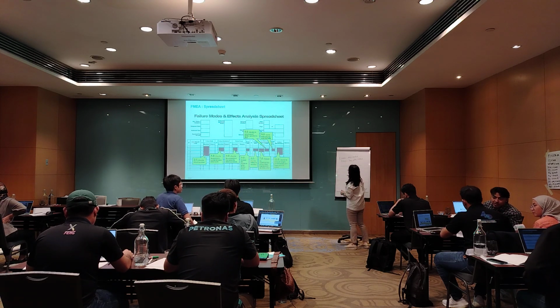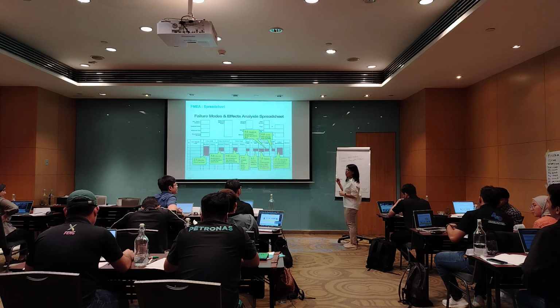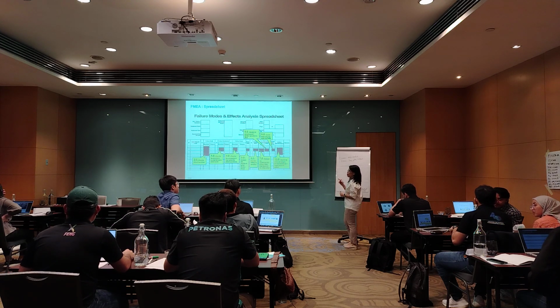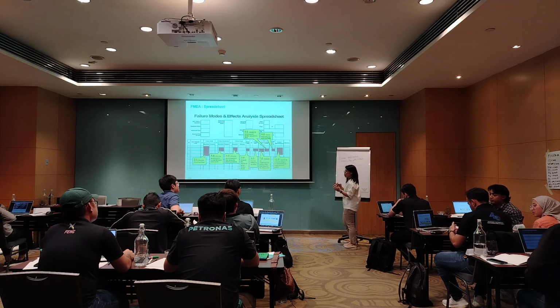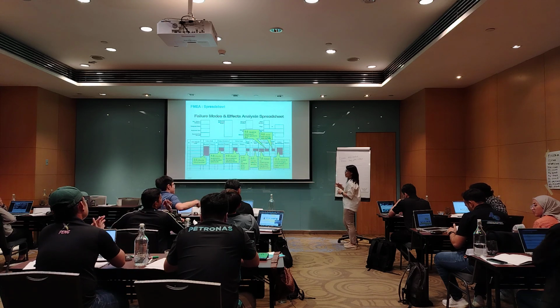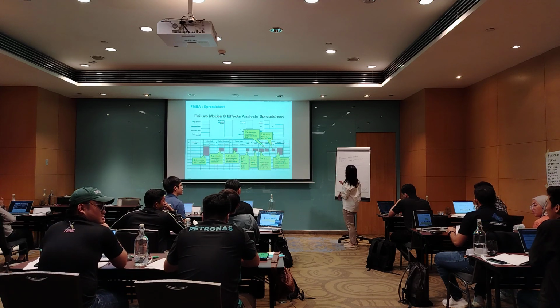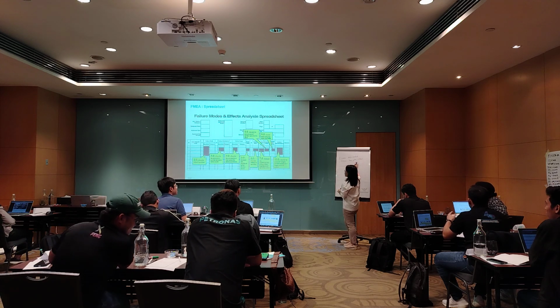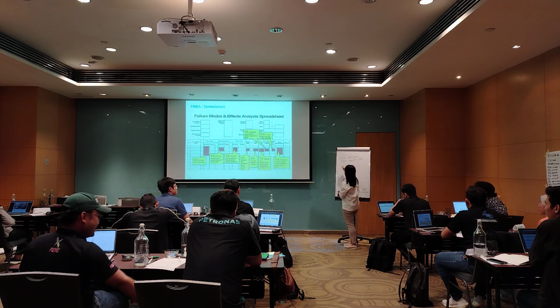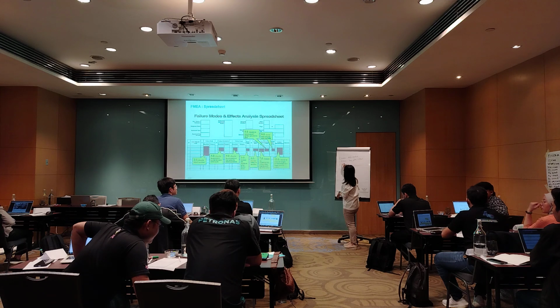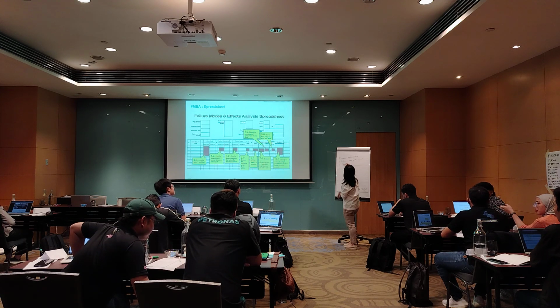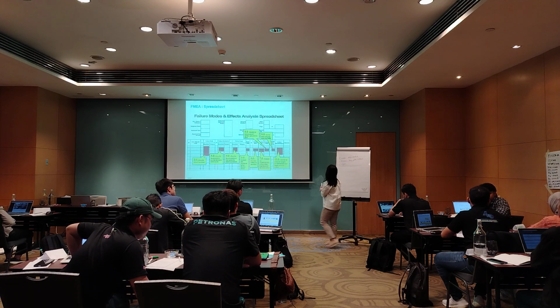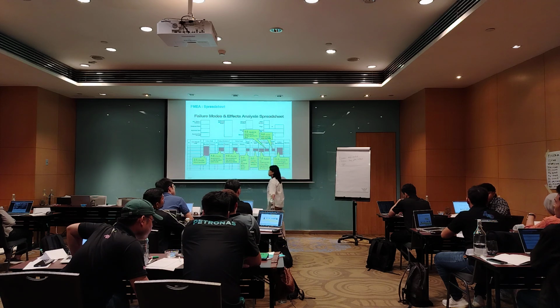Any more? The pump is faulty, then the motor is overheating due to the pump. Okay, overload in a way. Two first, we keep it simple first. Effect. When the motor overheats, what will happen?